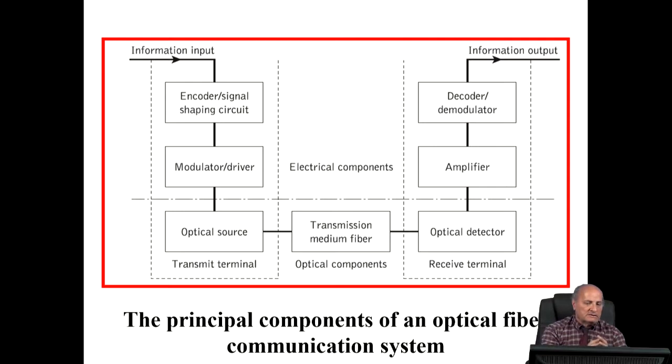This is a simple block diagram showing the main concept and the components used in intensity modulation direct detection. We have the information input, the message, and we have the drive. This is the electrical to optical interface. The data is embedded in the intensity of the optical source and transmitted through the link. In the receiver side, we have a photodiode to convert the signal from the optical domain to the electrical domain, and then it is demodulated in the electrical domain.